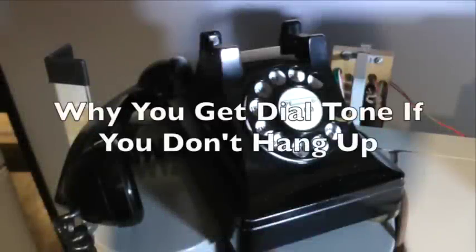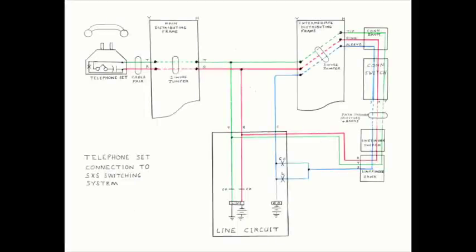If you're the called party in a step office and you don't hang up after the calling party has, you'll get dial tone. Here's why. So here's the calling station hanging up, and here's the called station remaining off hook. Since the calling station is hung up, the connector releases and ground is removed from the sleeve lead of the connector bank, which causes the cutoff relay of the called station to release.